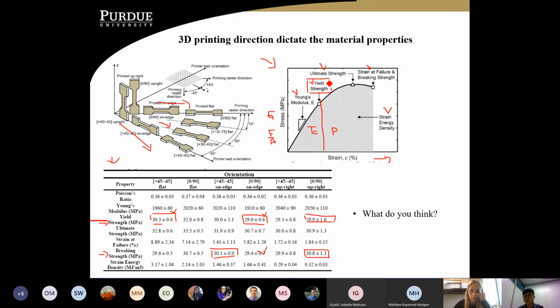Therefore, it is very important that whatever material you design with, you look at its yield strength, so that when you apply a load to test it, that load is not going to surpass the yield strength, so that the material won't fail.